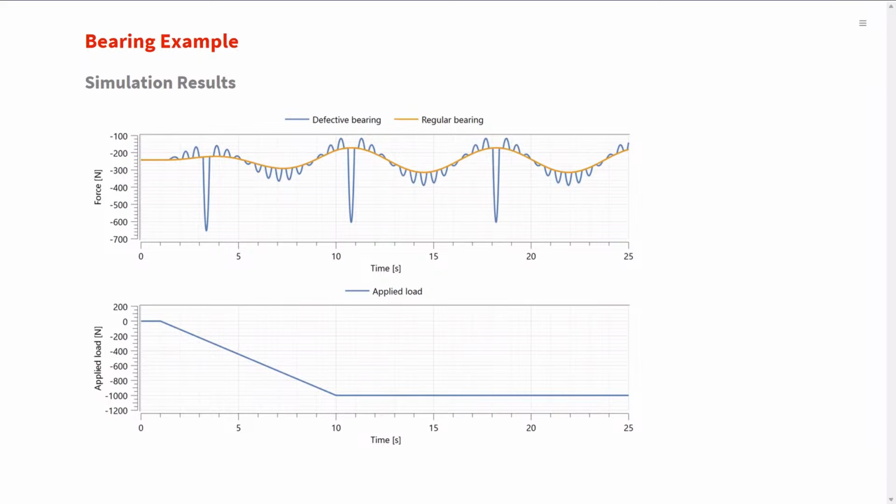Right, in this simulation, we are examining the forces on the roller bearings, where one of the bearings has been introduced with a 0.1 micrometer defect. This defect translates to an approximate impact of 500 newtons. You can check our documentation to calculate the corresponding force from the defect size. For ease and clarity in our model, we represent this defect through a force equivalent method, which simplifies the integration into the system dynamics.